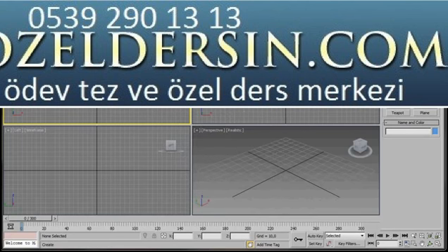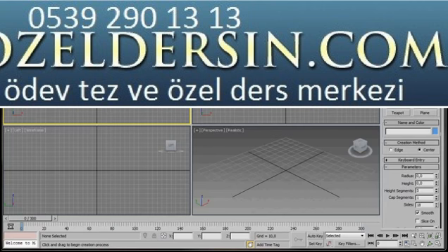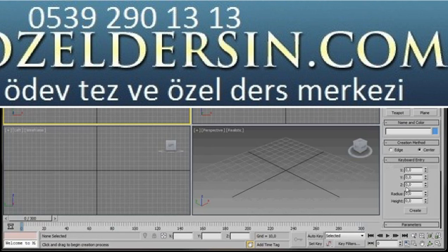We're going to create the flagpole first, so we'll go to the Create panel, Geometry, and then scroll down to Cylinder. We want to create it in the top viewport, so we'll just click anywhere to activate it. Then we're going to come over to Keyboard Entry. Notice here that we have X, Y, and Z axis. It's all set to 0. That's perfect. We're just going to type in radius of 2 and a height of 180. Then click on the Create button.